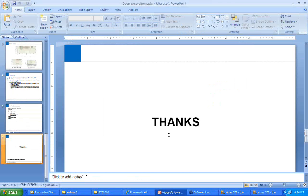So all I mean to say is all the x and y will be on the face of the plates. So the alignment should be done in such a way that the major moment, when we see in the result, should be my rather than mz. Having that in mind, you can make your own criteria for aligning the cross section.